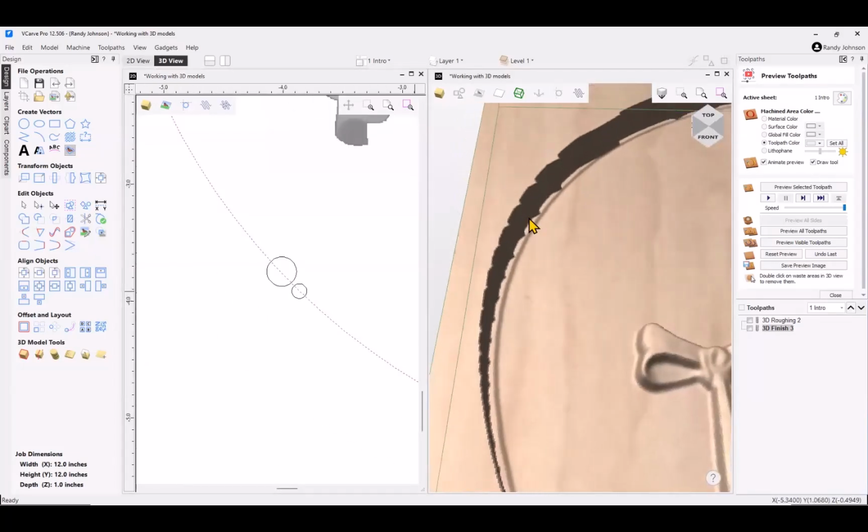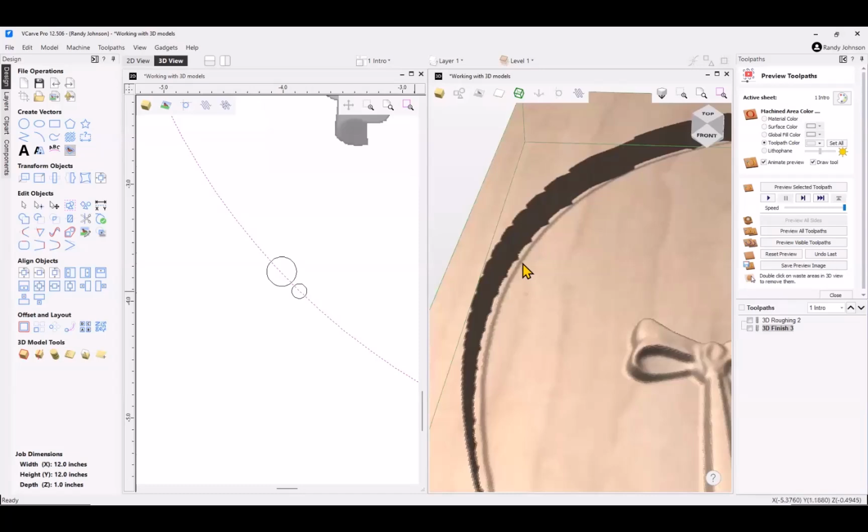Now, in 3D carving, this is actually a nice arrangement. Setting aside the fact that you may not like this rough edge, and I'll show you a way to deal with that, it's nice to have the 1/4 inch bit cut a little larger than the 1/8 inch bit. Remember, the 1/8 inch bit is going along the surface here, and if it were to hit against that wall, it's that full 1/2 inch. It's like slamming up against a brick wall with that little tiny bit, and you're going to get a lot of chatter and potentially break the bit. So it's actually nice to have that extra clearance around there for that 1/8 inch bit, so that it has an advantage that way.